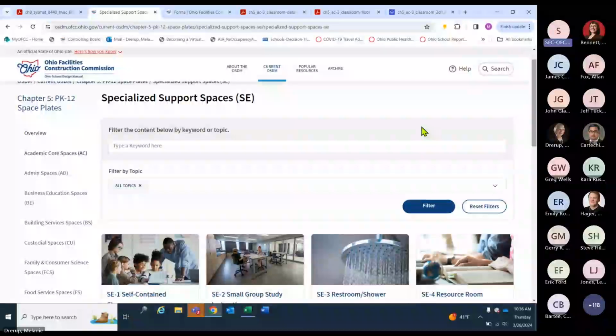We also received another question from the chat from Todd Winters. They asked, package rooftop units are no longer acceptable. Is that facility-wide or just for classroom and office space? The package units have not been acceptable. We want the HVAC units to be accessible to our maintenance men so that they can get those filters changed. So we try not to utilize any rooftop units or packaged units.